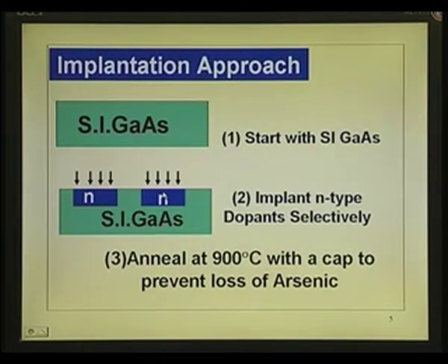silicon. And when you do implantation, you have total control on the number of atoms that you are putting there. You can virtually count. You count by measuring the current. When you implant, there is a beam current. Okay. So, if you implant for 10 seconds, I into T gives you the total charge divided by Q gives you the number of atoms that you have implanted.